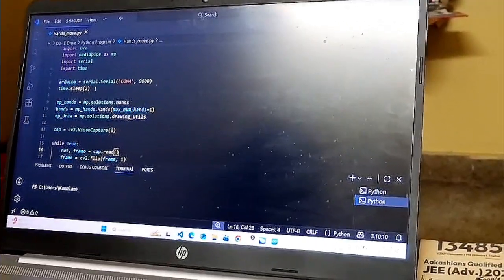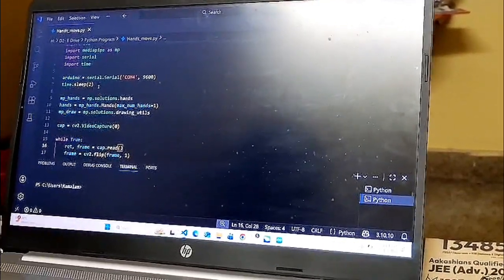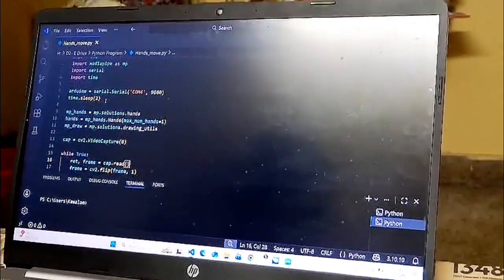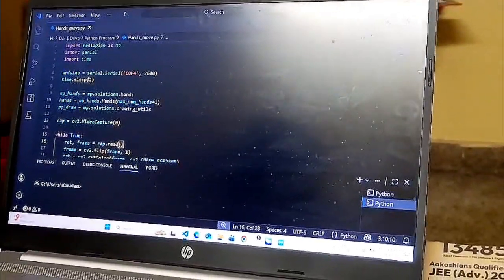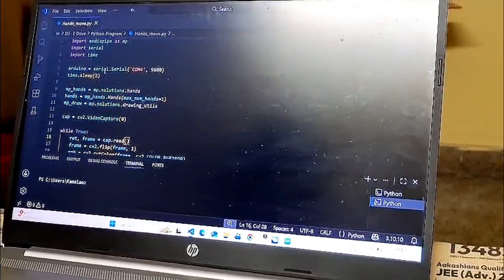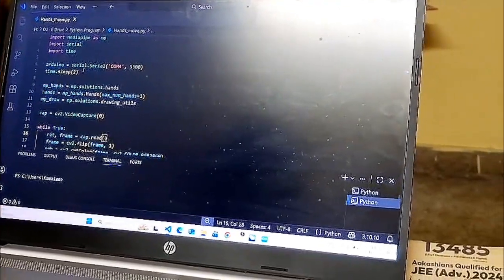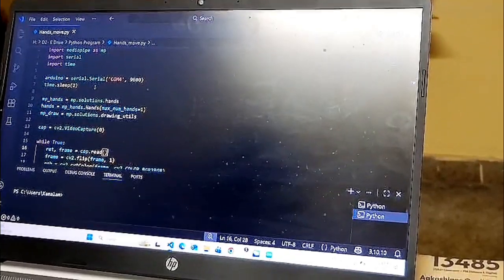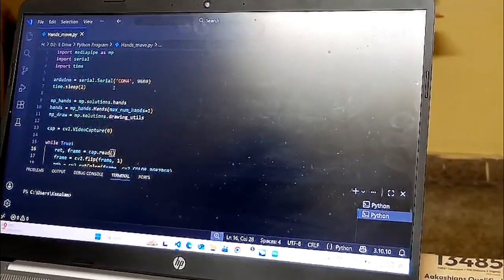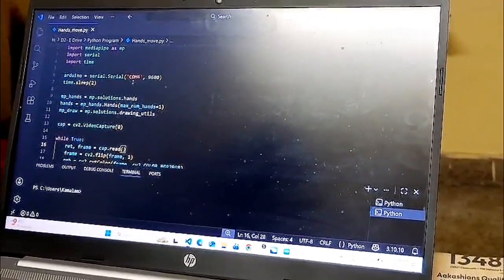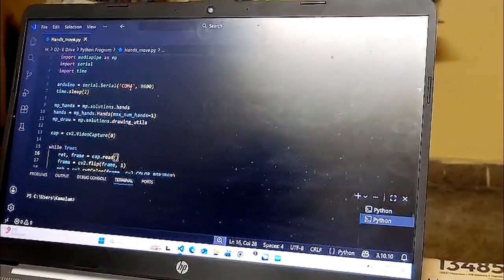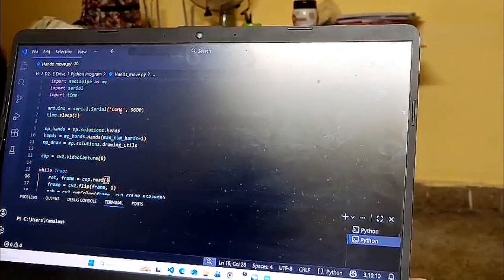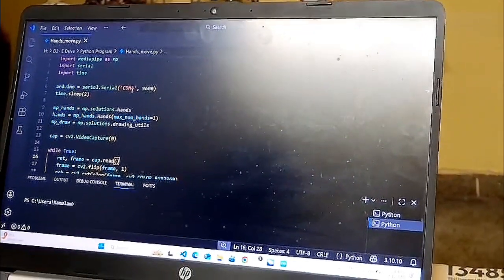And then this code is very simple to write. Here I declared the variables. As per my knowledge, I declared one of the variables as Arduino. In this Arduino, serial is a module, which we already downloaded. Along with this module, we specify which communication port is to be connected to the Arduino. So for that, the Arduino Uno, COM port 4 is to be connected. Suppose in your Arduino Uno board, whichever port is connected, you have to choose that particular port.